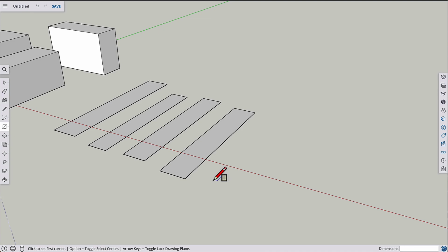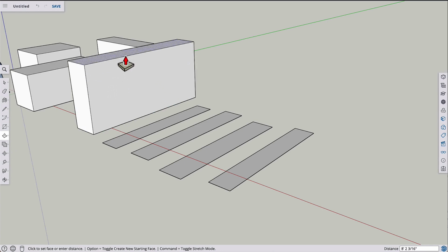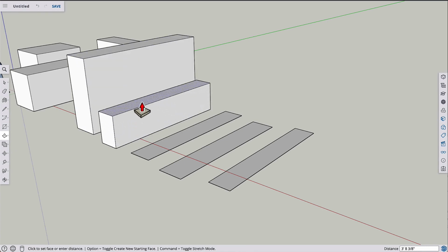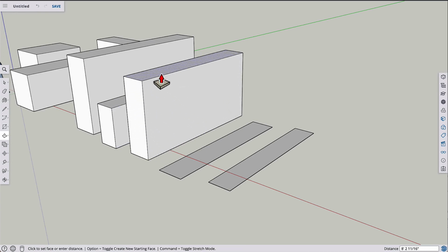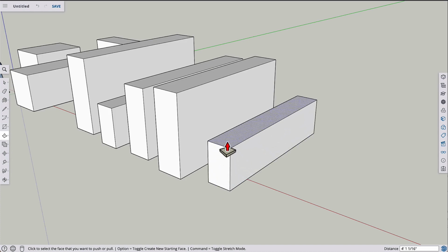button to draw, and SketchUp will allow this. However, we want to break that habit. For most tools, SketchUp works better if you click to start and click to finish the tool. With this row of rectangles drawn, we'll pull these up into boxes with the push-pull tool. But again, be careful to click once to start pulling a surface and click again to finish. 1 click to start, 2nd click to finish, and pull these up to different heights.